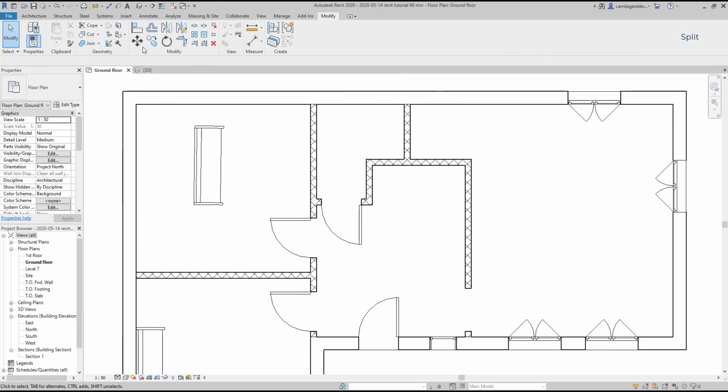As with the command align, I pick the wall face, which is my destination, then select this axis, and you can see the sofa aligning at the wall perfectly. Then press escape twice to exit the command. Now let's learn to split an element.